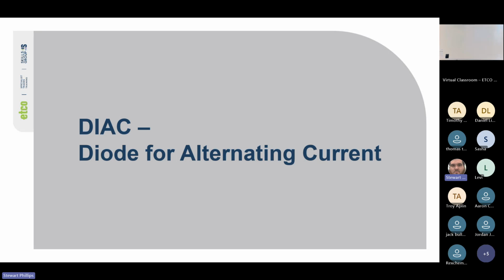So when we first look at a diac, it can seem a bit pointless. It's like a diode that works both ways. But that's exactly the point. The diac doesn't care about polarity, it cares about voltage. It stays off while the voltage across it is low. Then when the voltage builds up to a certain point, it suddenly breaks down and conducts sharply. That sudden switch on provides a strong short pulse of current. That's what makes it so useful for triggering other components like triacs, which we'll get into after this, which need a quick, definite pulse on their gate to turn on properly.